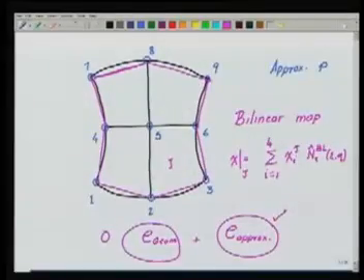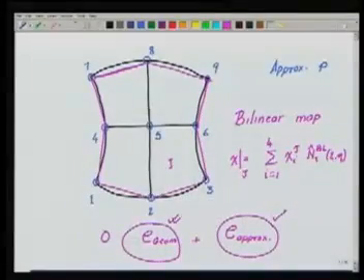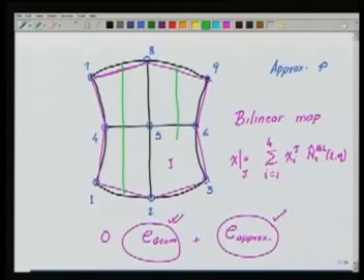Okay. Now, what will happen in this case? This error will be dominant, or at least significant. Need not be dominant, but it will be significant. So how do you control this error? One way of controlling this error is to say, fine, let me refine the mesh. Can I take a finer mesh? Okay. Now see what we are doing.